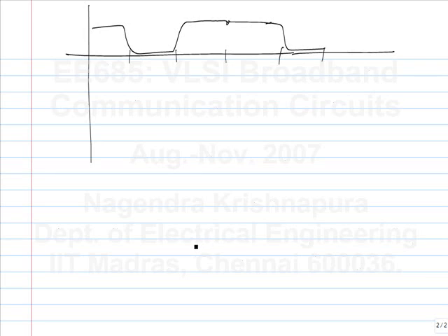So, if you have a number of samples, first of all, can you do it with sampling once per symbol period? Sampling only once in every symbol period, can you figure out if it's early or late? Okay. You want? The distance between them should be in such a way that we can make sure that there are no more than 2 clock transitions within the period. Okay. Then we will be able to flip flop. Okay, so how many do you need? 2.